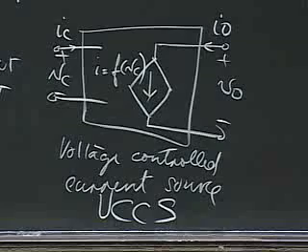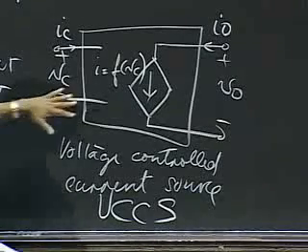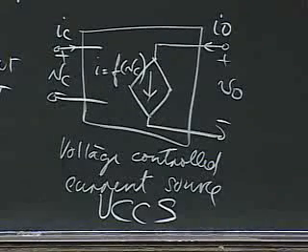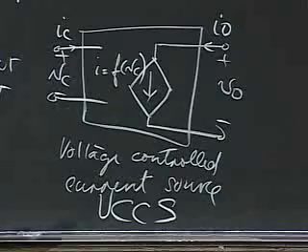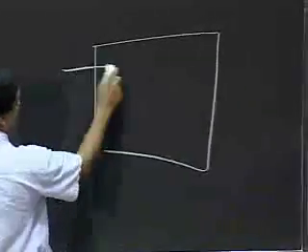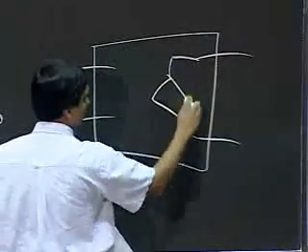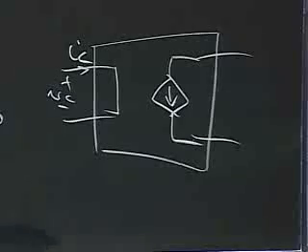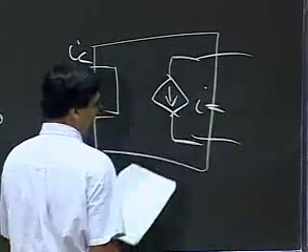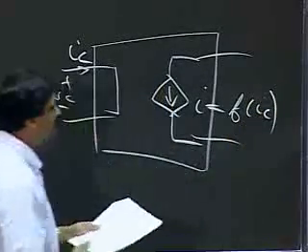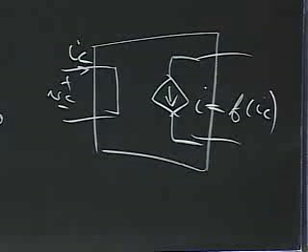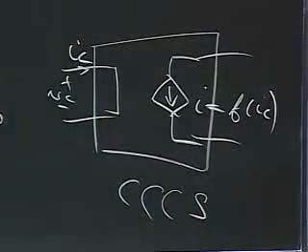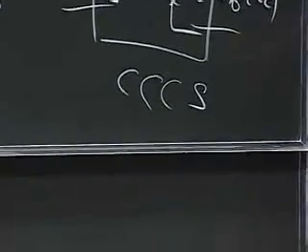So, in like manner, I can also devise other forms of sources. You can think of this as a device where a voltage controls an output current. You can think of all other combinations: current controlling current, voltage controlling voltage, current controlling voltage, and so on. Another example: in this situation, my output current is controlled by an input current, IC, and I claim that I, for this one, is some function of the current IC. It's another dependent source where the output current through its output port is related to the current IC. And this is a current-controlled current source.